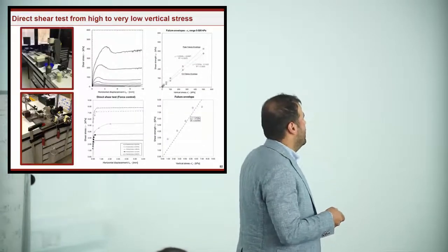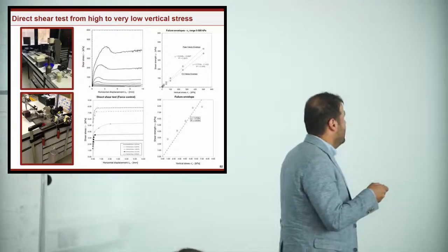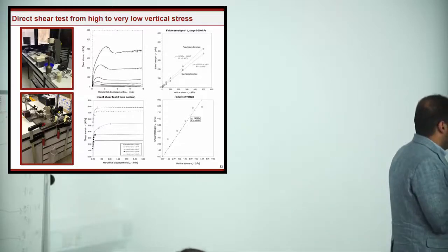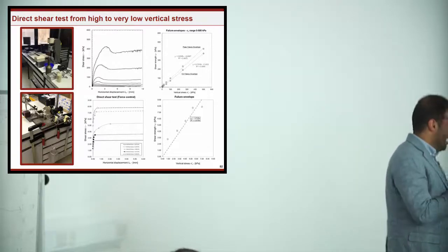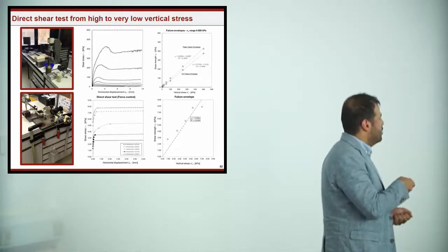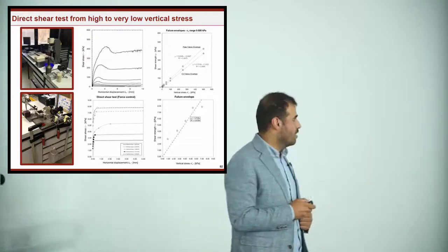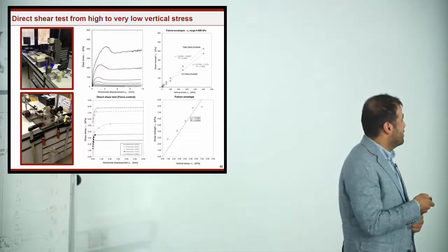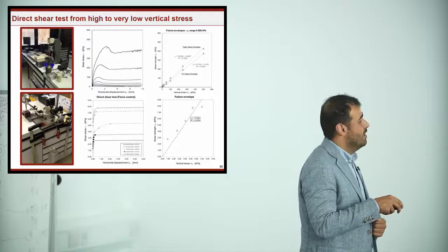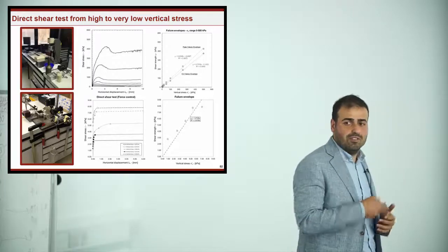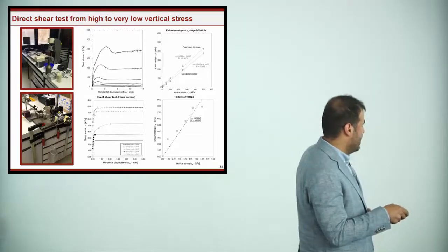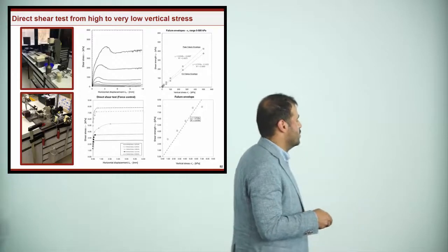So we did the test by using an advanced shear test apparatus, a tool that was built where the stress was applied by pouring sand inside a box that was applying the shearing, and from the top there was a box that was applying the confining stress. As is confirmed by the results in the literature, we got a shear strength angle that is very high. We have 52 degrees of peak that is reducing with the increase of the vertical stress. Here are represented both the peak and constant volume shear strength angle.